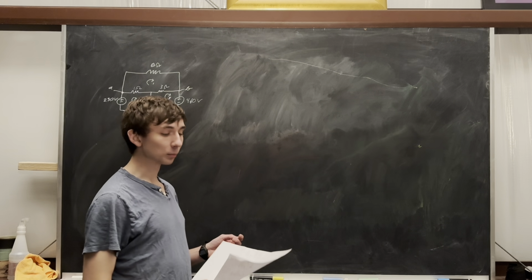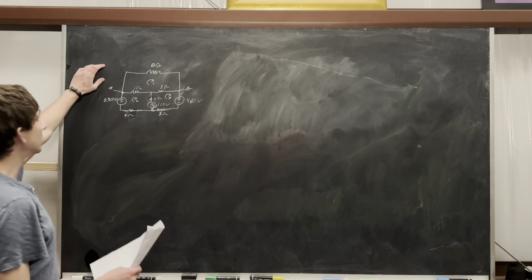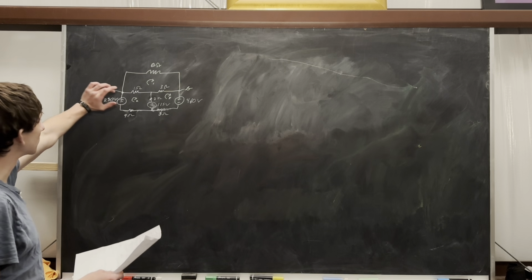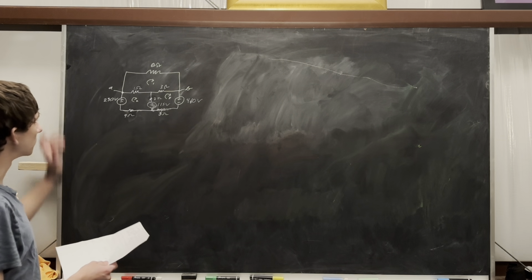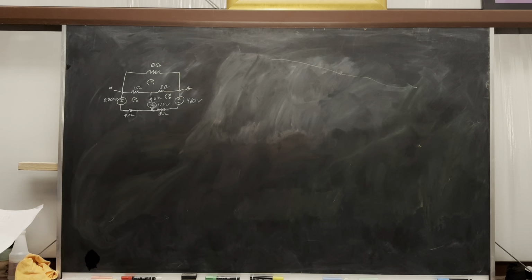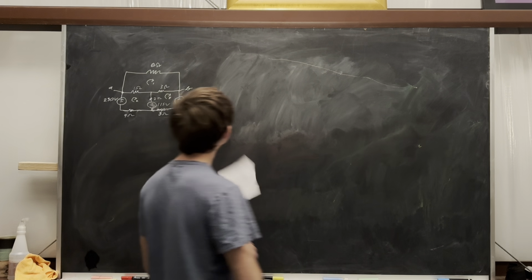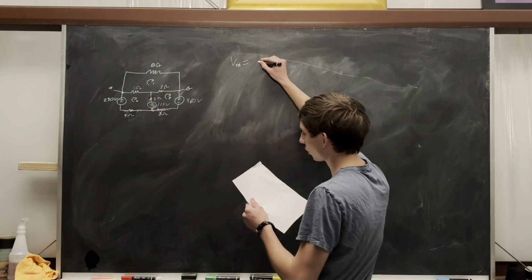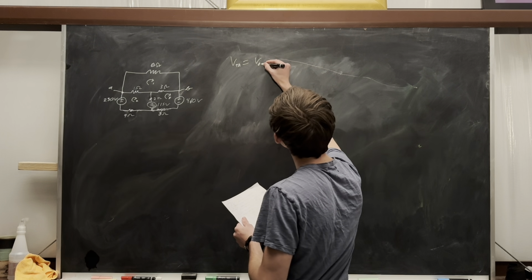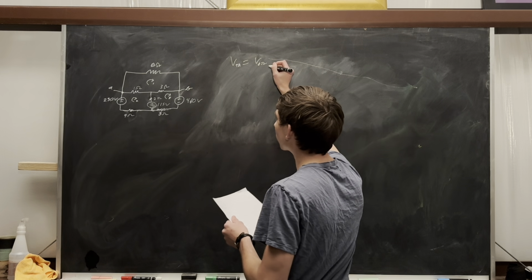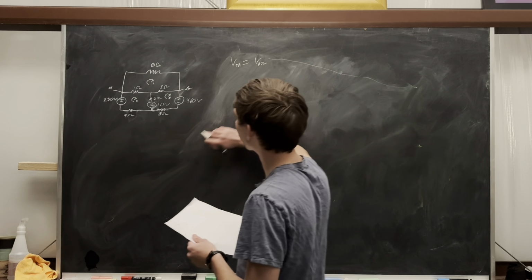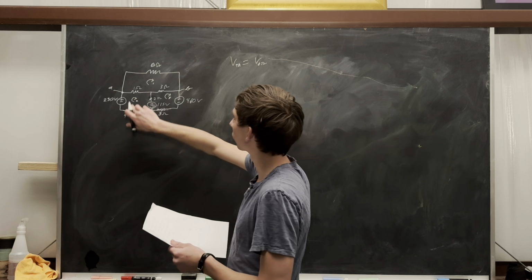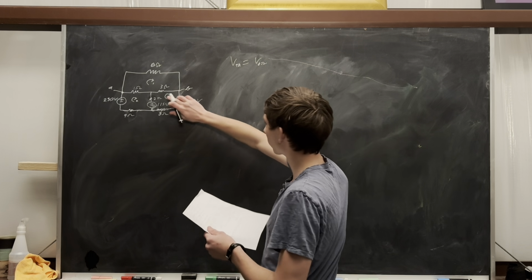Okay, so this is the second problem I came up with. This is the circuit from problem 437. I just stuck a terminal here and here, and figured it might be fun to calculate the Thevenin equivalent of this. So for Thevenin, it's just the voltage across the 6-ohm resistor. You can solve that pretty easily using mesh analysis. So I already have them labeled here, but called this loop 1, called this loop 2, and this loop 3.